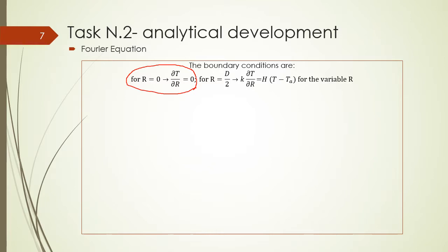It means all the heat transfer is from the center to the outer part of the potato, and to the skin of the potato we can use the energy conservation, saying that the heat transferred to the skin by means of the conduction, the first member, is the same as the heat delivered to the ambient by means of convection and radiation.